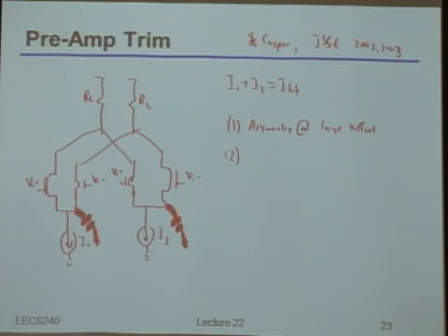Oh, absolutely. You said, is the V star changing as you move the currents around? Absolutely, but notice the limit is clear. The limit is if I put all of the current on this side versus all of the current on that side. That's kind of like the plus and minus. So if I push it all the way to the plus, my offset is basically the difference in V star between the big device and the small device. And indeed, the way you control that difference in V star is by how big you make this big device relative to that small device. But it does indeed say that if you want to get a big offset range, you basically need a big delta V star.